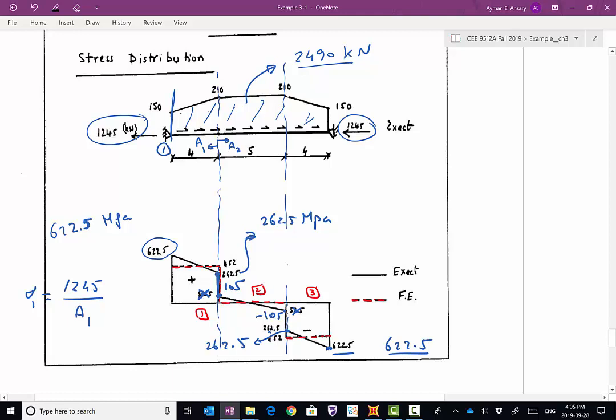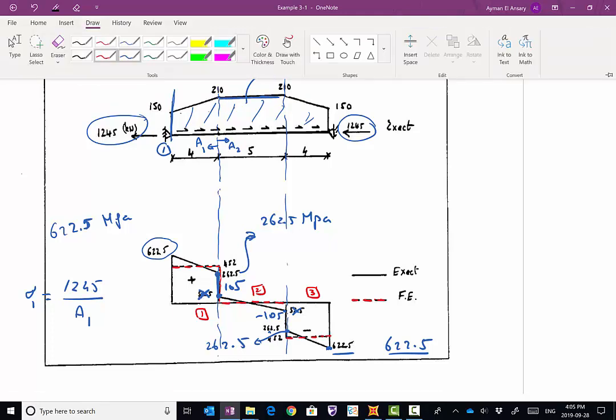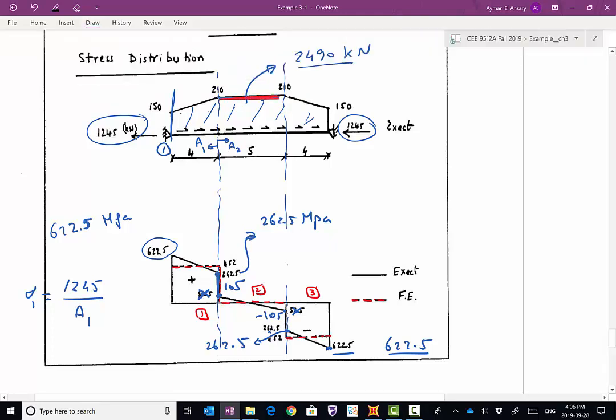So based on our understanding, we need to understand what's happening here and why the finite element solution is not capturing the exact value. The best thing to understand is that the load acting on element 2 is a uniform distributed axial force, so we're expecting that the exact solution will give us linear variation in stress. So this is linear stress. That's from exact. Let's write it in blue because we referred to exact as blue. So exact is blue. So this is linear stress.